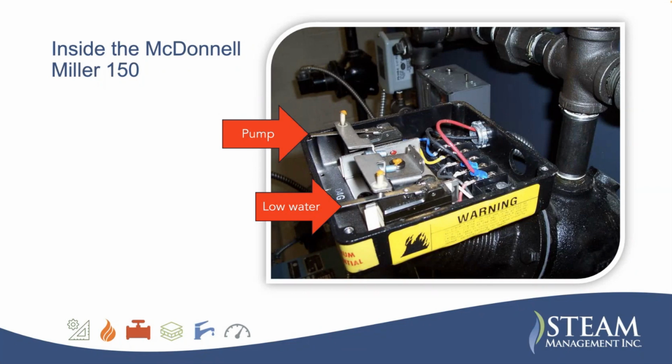Now you'll notice that there's some wax that they put on these. That means you're not supposed to touch these. I've had service technicians that will remove that and try to adjust this up or down, and it puts you in responsibility for this, and you don't want that to happen.